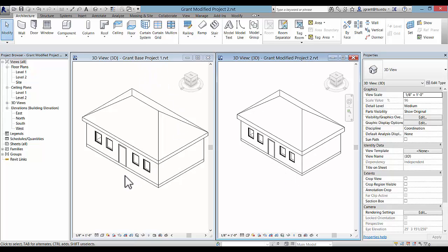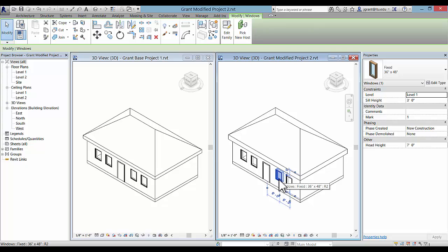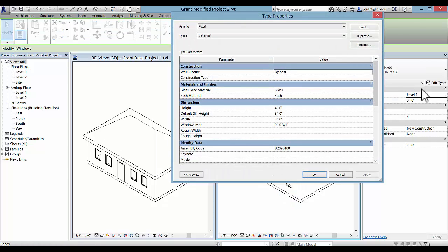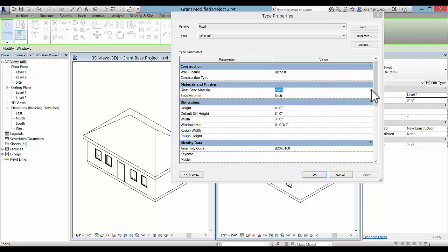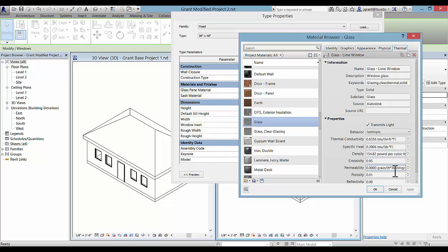So now we're ready. We're going to keep the same location, although the location does establish the weather station and weather properties for that area. You could change the glass for the windows, but once you look at the analysis, you'll be able to determine whether you need to work with stronger thermal properties for that glazing.